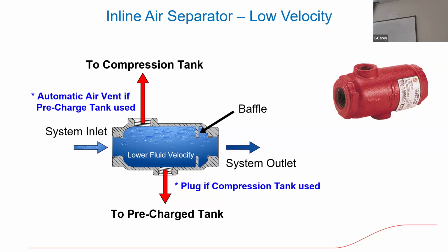The way this thing is manufactured is this diameter here just allows that 4 to 5 feet per second to drop to a half foot, 6 inches per second. So it becomes like a wide spot in the river, and the water slows down. So the air that came out of solution when it came out of this heated boiler up through the supply pipe hits this low velocity area, air comes out of solution. It gives it a quiet spot. And these bubbles will then be vented off the top here with a high capacity vent.